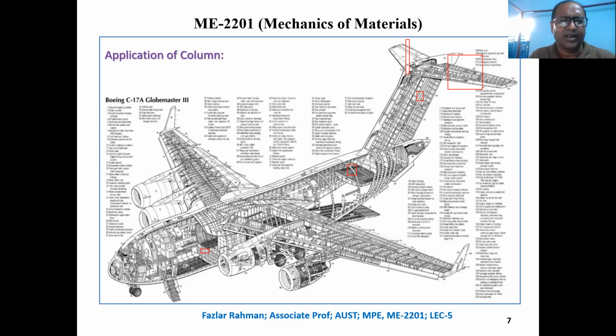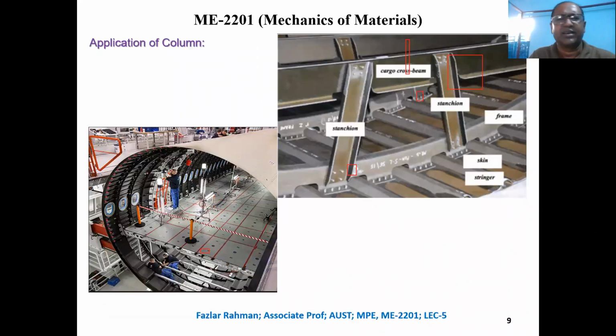Similarly, if you look at another picture, this one is a picture of a real aircraft photograph. You see right over here, this is a floor beam, and they have one every 20 inch or 24 inch. One frame of beam over here going left side to right side. They might have one more over here, one more over here, from front to tail.